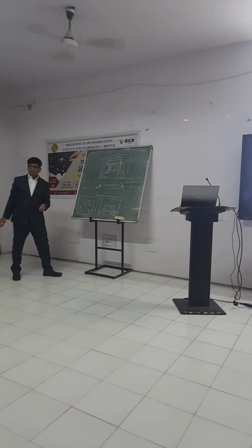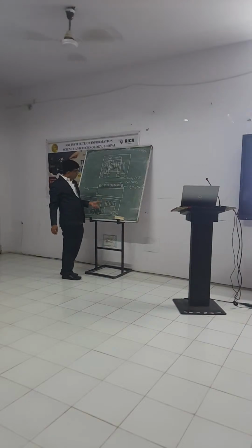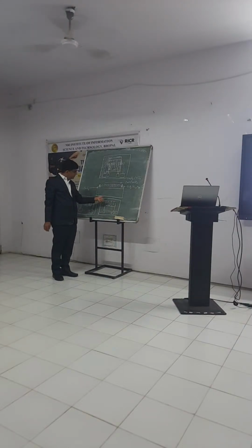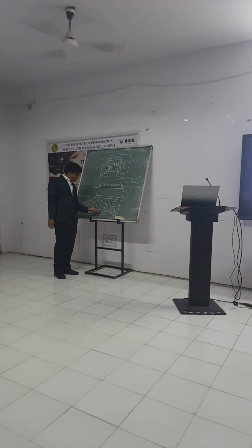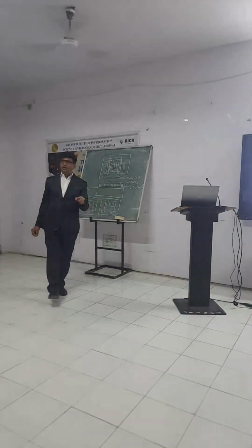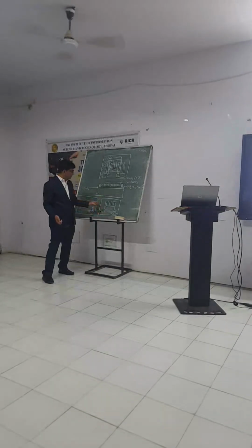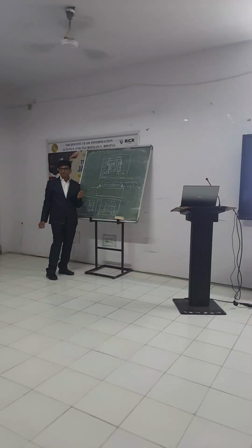Clear? Understand? So now we have to pattern my IDE electrode for measuring the current or resistance of the device. So again, see, in lithography you have to open this window and this window both. If you are not opening this window, then what will happen? Again, how can you make your contact with the heater element? Clear? So now after deposition and patterning of your IDE electrode, what is the top view of your device? This is the top view of the device.